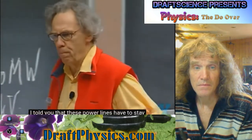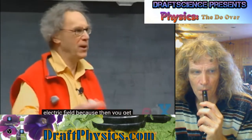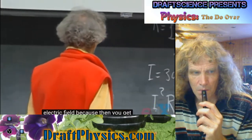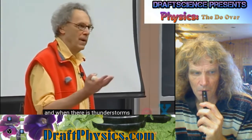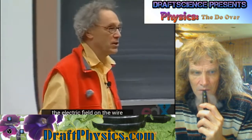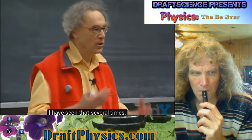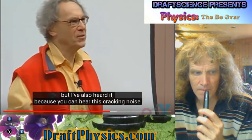I told you that these power lines have to stay away from the 3 million volts per meter electric field, because then you get corona discharge. And when there are thunderstorms in the area, it can actually push up the electric field on the wire, and you can get corona discharge. I have seen that several times. Not only seen it at night with my naked eyes, that you see the power lines glow, but I've also heard it, because you can hear this cracking noise of corona.